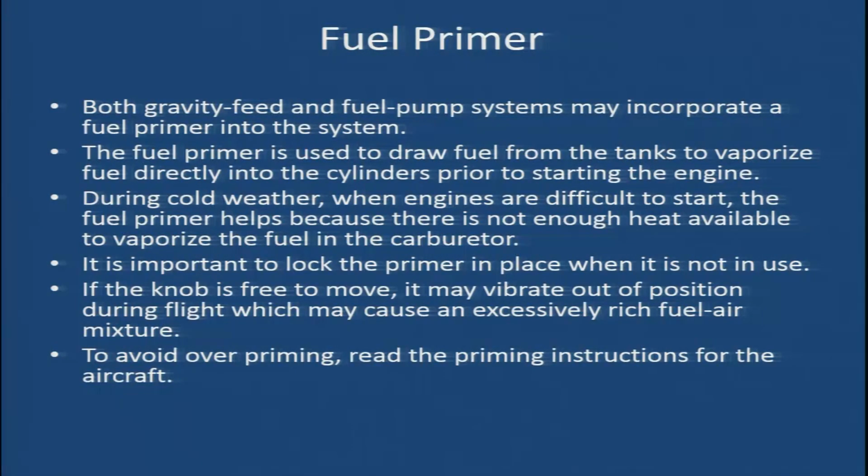If it is left unlocked and the knob is free to move, it will vibrate out of position during flight and may cause excessively rich fuel mixture. To avoid over priming, the priming instructions need to be read from the aircraft manuals. The recommendations of the manufacturers need to be followed.